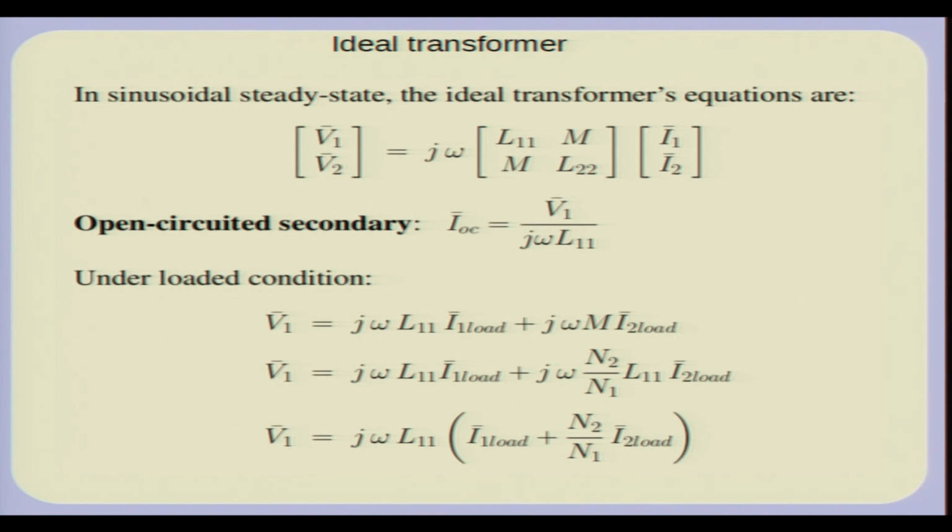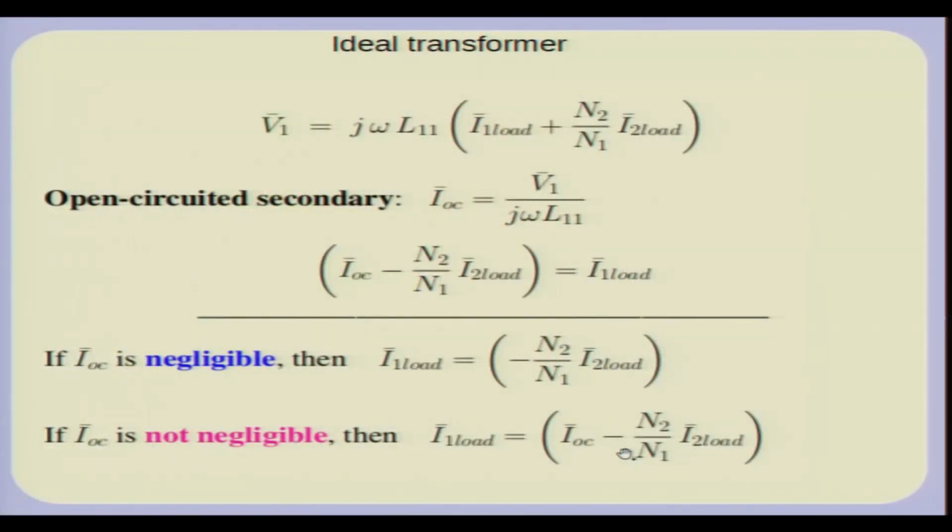One of the important points which you should remember is that this transformation to algebraic equations works quite well for sinusoidal steady state conditions, but we have to be a bit cautious when we try to apply this when there are DC currents flowing, etc. So, please be careful, do not apply these for any general situation. You have to check whether this applies during sinusoidal steady state conditions.